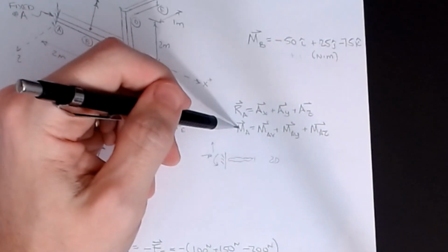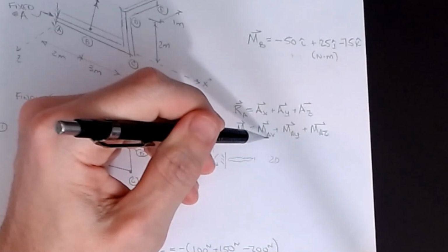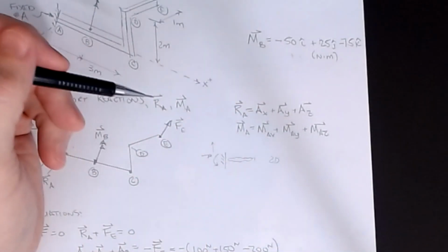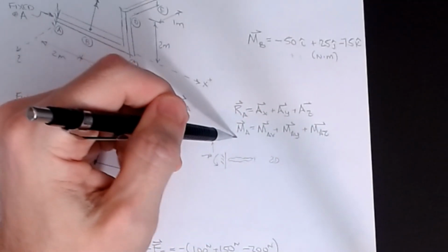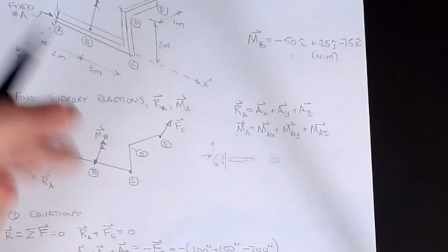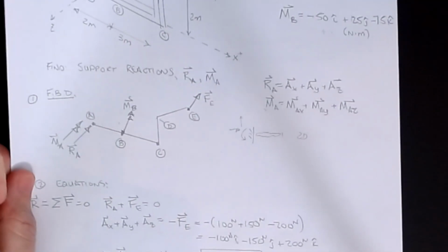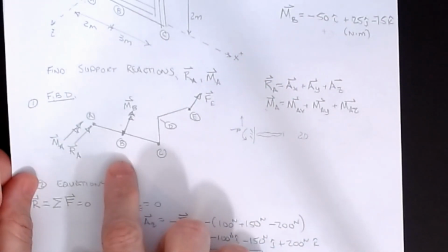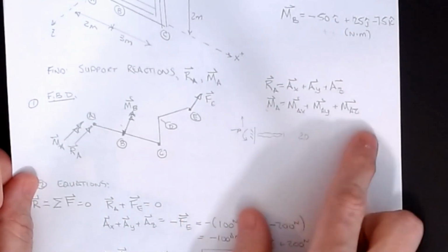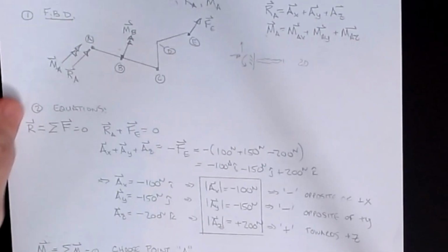Okay, and then the moment, this was a moment about a Z-axis in 2D. Well, now I have a moment about an X-axis, a Y-axis, and a Z-axis. But again, we can write all of these as vectors, so they're just vector sums. So I can take that big vector and split it into little pieces. And that will be one of the tricks that we'll have to do in order to solve this. While we're mandating that the resultant effect is 0, we're going to be taking these unknowns and splitting them back into Cartesian components, which is a very common practice.